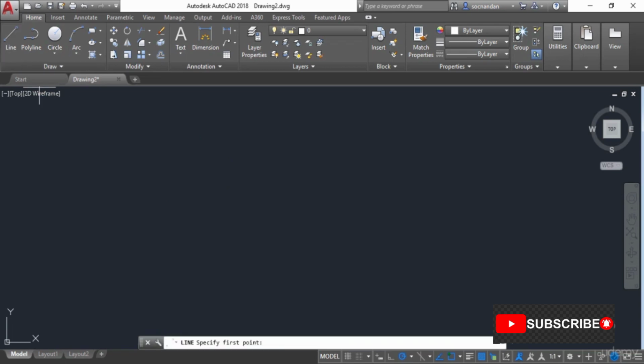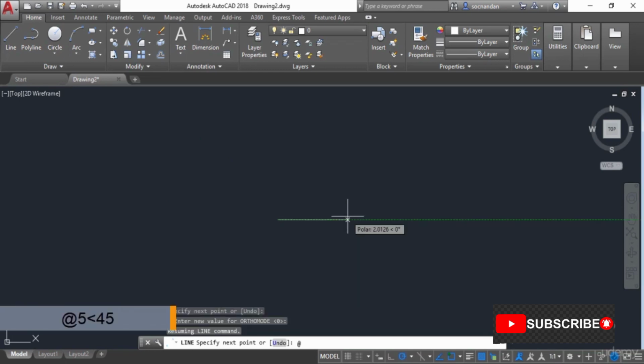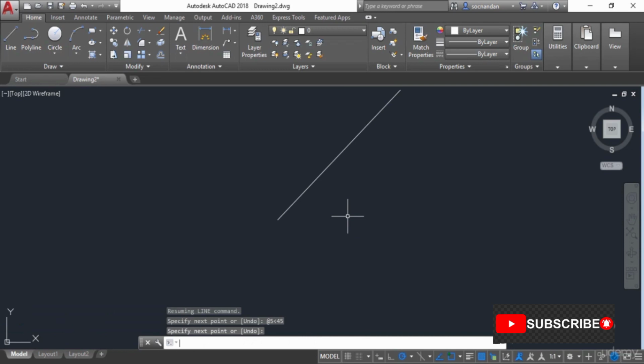So I'll go to this line command, click at any point here, and now I'll make another line which is inclined to an angle of 45 degrees. So let's type @, and the length of the line should be 5. So type @5, angle sign, 45. Press enter, and here we have it.